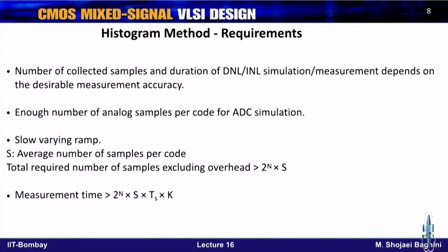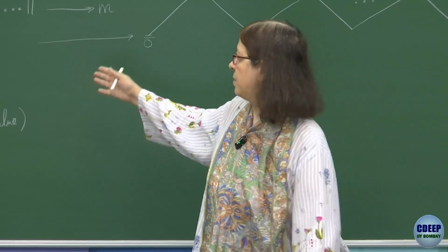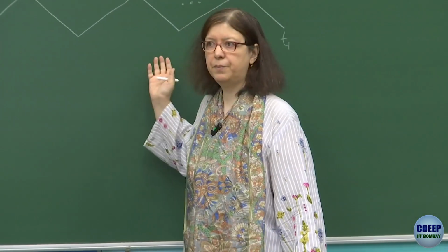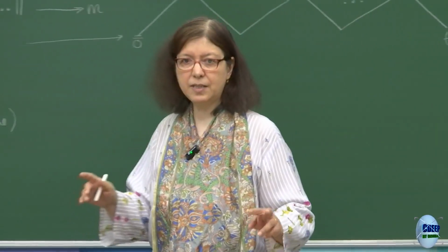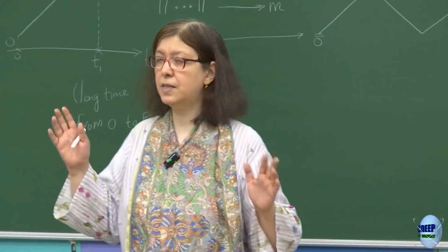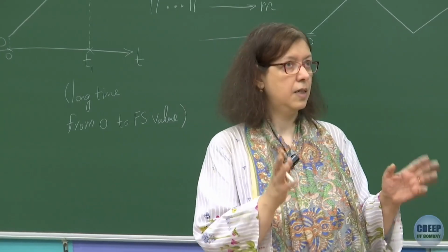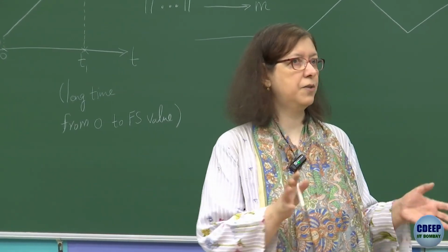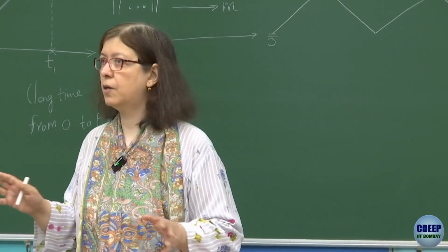You can do the same thing in simulation, but in simulation you don't have any memory per se that you eventually store them in. It's software only. There's no external memory. That's why K is equal to 1 for simulation. Otherwise, for simulation also, you can give the same periodic triangular waveform to the ADC. Now this ADC from simulation is not an ideal ADC. It is a post-layout extracted ADC with Monte Carlo, so random variations will be included, also corners.